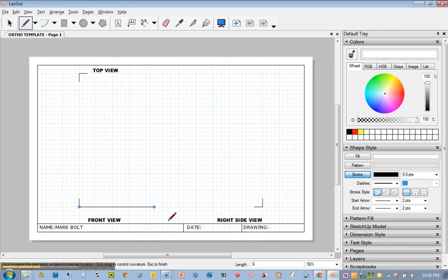You'll actually notice I'm going to move away here. You're going to notice down here that this number will reflect what I type in. So once again, let me go ahead and just move my mouse in the direction I want a line to go in. Make sure you always move in the direction you want your line to go in. Type in the number, in this case 6. Don't need to put the inch symbol, just 6. Hit enter. I have a 6-inch line. Now I'm still in line mode, so I'm going to move up. That was a height of 3, so I'm going to type in 3, hit enter, and then I can just continue moving. And I can actually do this without having to type in anything. And then once I get to the first point, the box is enclosed.